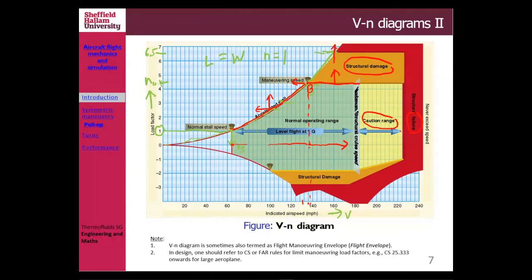And if you keep going with a certain speed, for example if you fly into supersonics, you're going to have wave drag and so on. That also could damage your structures as well. So now sometimes we consider what we call the maximum structure cruise speed.